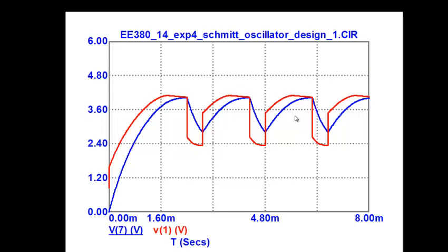Okay, it oscillates, but then what do you see? It does oscillate. Can you see a problem? Duty cycle is? Note all the problems here: it is hardly a square wave, it is rising and then becomes like this here and then goes. Duty cycle is definitely not 50%. The on time is maybe 3 times the off time here. So the duty cycle is not being satisfied and is highly distorted.